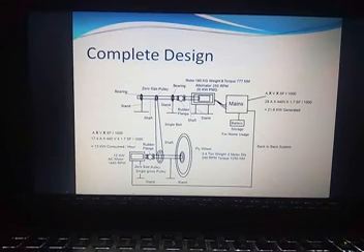Thereby, when the flywheel is rotated at 240 RPM, we are trying to make the other side of the pulley rotate at 250 RPM. Thereby we are connecting a PMG of 20 kilowatt which is rotated at 250 RPM. The weight of the inside rotor is 180 kilograms and the rotor diameter is 11 inches. The torque is 777 Nm, Newton meter.